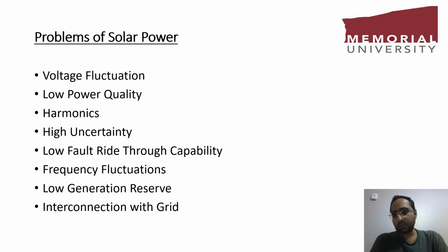What happens is that whenever there is an increase in load demand or a reduction in the load, frequency fluctuations happen. In that situation, the installed relays, which are rate of change of frequency relays, usually tend to operate, which disturbs power continuity.